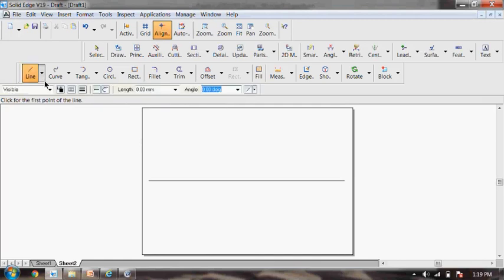So how to consider the square? Square by edge resting position. Go ahead with the simple angle method. Click on line, select 0.5 thickness. The square lamina is 40 mm. Type 40 length, angle 0. Then again 40, next angle is 90. Then again 40, next angle is 180 degree. Then again 40, next angle is minus 90. So this is the square.